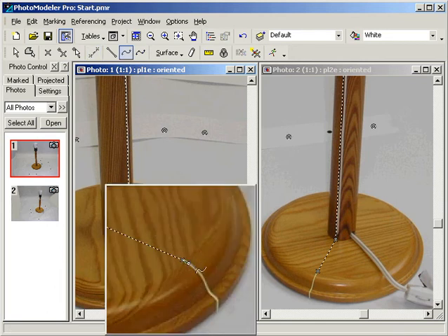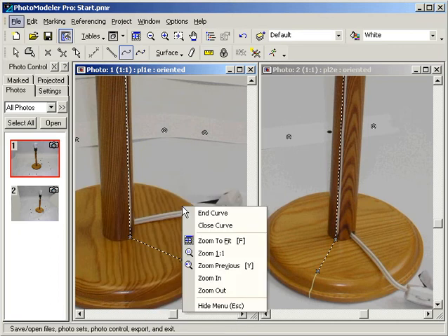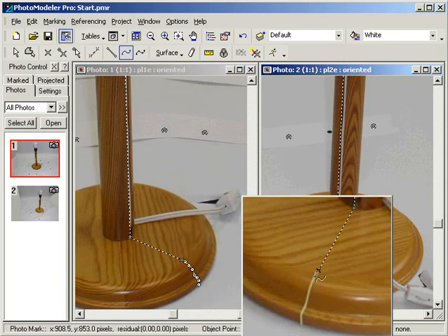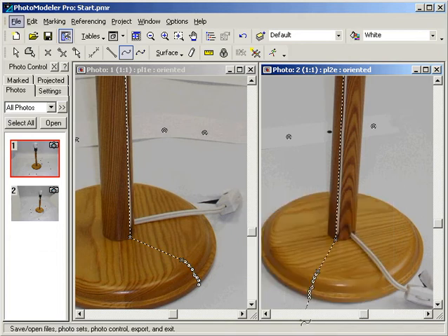We use the Alt Zoom to mark the curve points accurately along the curve shape. We try to mark the points close together as this curve has some sharp direction changes. We end the curve. Next, we will reference the new points and curves.